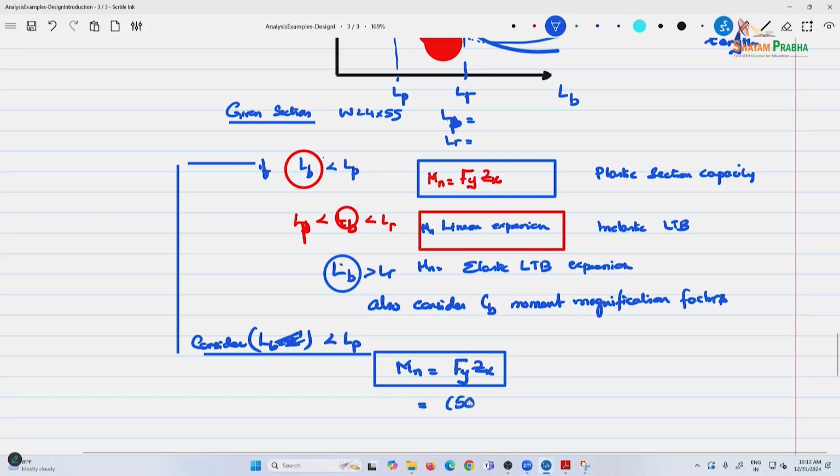Your Fy is 50 ksi, and 50 ksi is what you use. What do you use for structural steel here, 350 MPa, 400 MPa? Structural steel is 250 MPa, reinforced steel is higher.